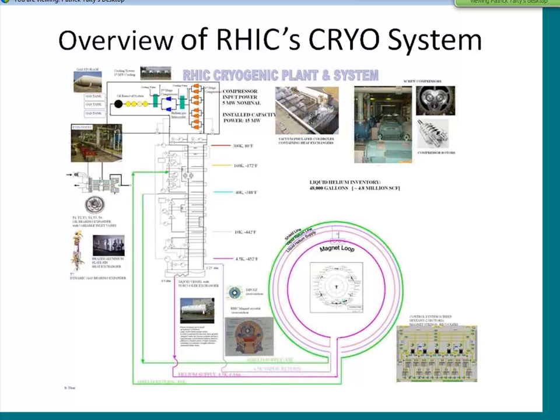very simple terms of a can of compressed air. When it's full and at room temperature, if you hold it in your hand and you open the valve, you squeeze the trigger, and the contents, the compressed air, leave that can. You have a constant volume container, the can that's undergoing a rapid depressurization, and as it undergoes that depressurization, there is a corresponding drop in temperature.